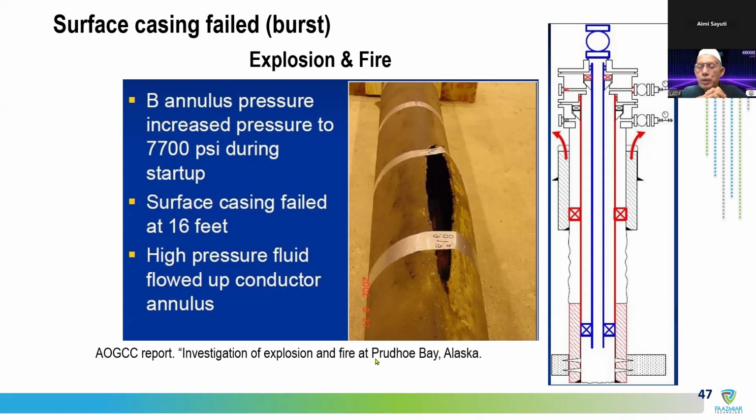And the problem with drilling fluid when we do cementing is that at the interface between the top of cement and the formation, there will be a mixture, a contamination. That's why in cementing we recommend using a spacer to isolate the cement and the mud. Then of course any contamination is between the spacer and the drilling fluid, so it's still under control. It's not going to be much of a problem.